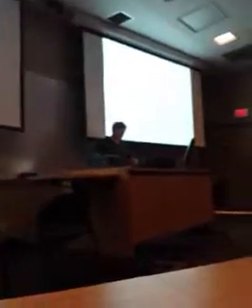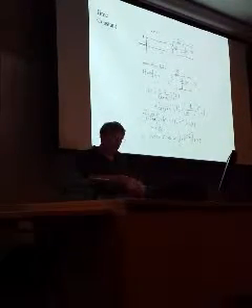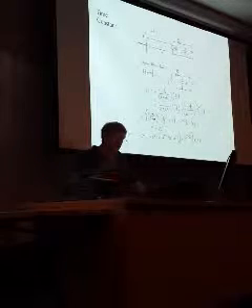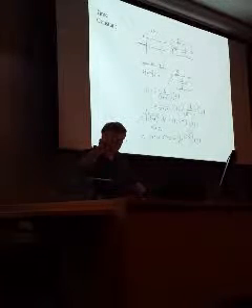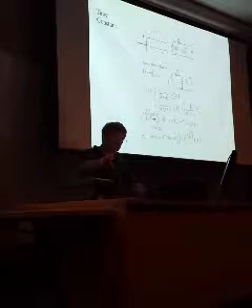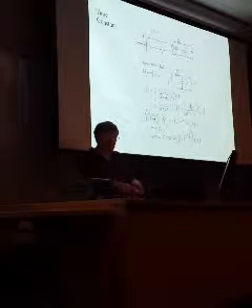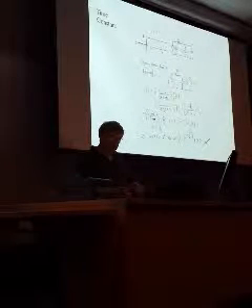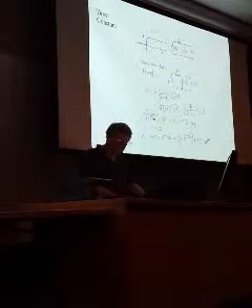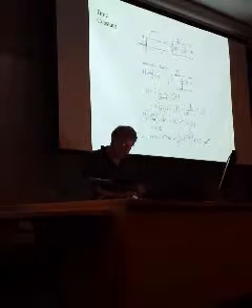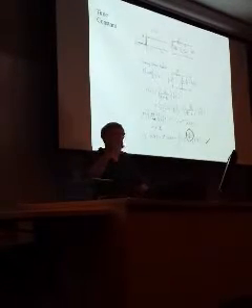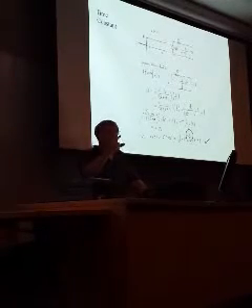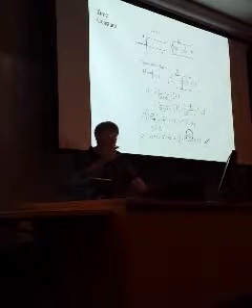And, if you're not convinced, this is actually the kind of analysis. If you do the Laplace transform of a unit step, it's 1 over S, and R is R, and the impedance of the capacitor is 1 over SC. And so if you do the little voltage divider equation, it turns out that in closed form you can solve it. And so you end up with this exponential with a time constant. And that time constant is 1 over RC.